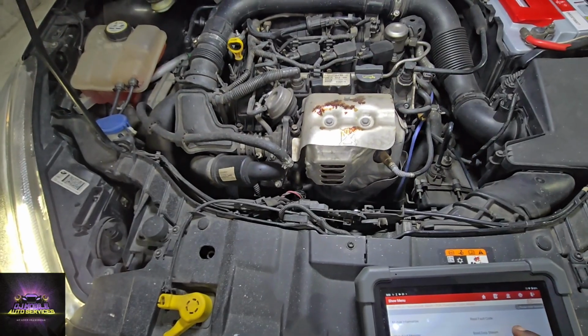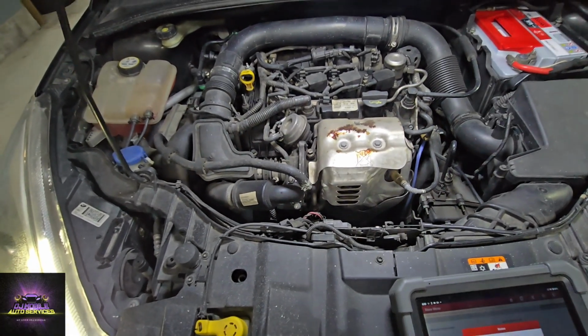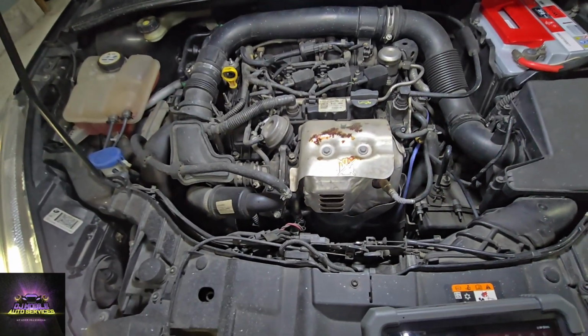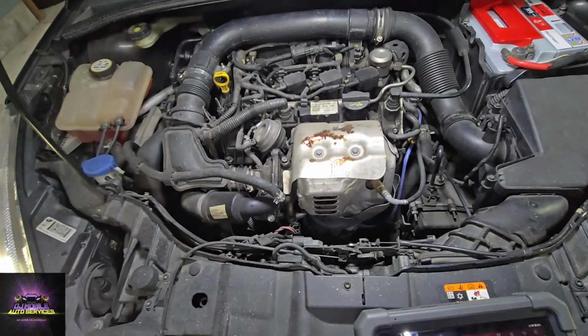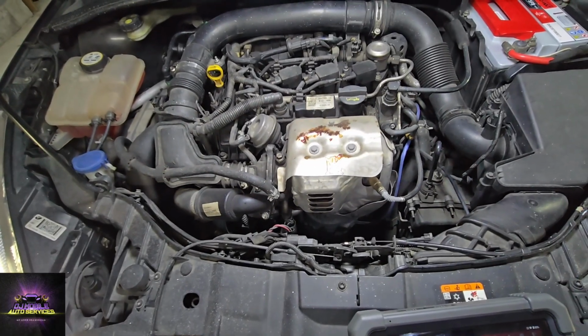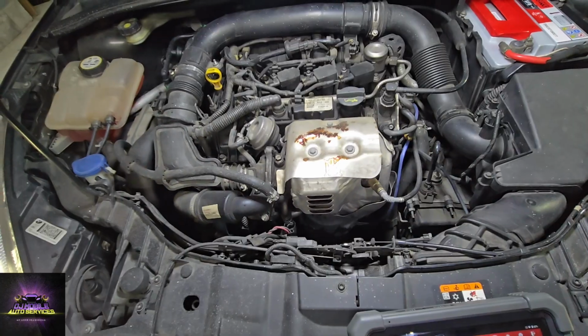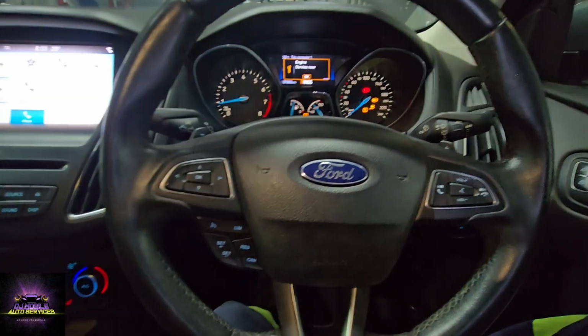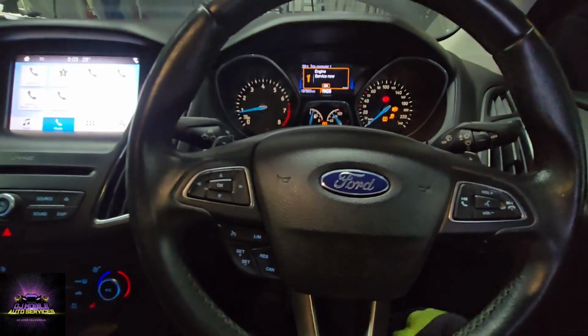Matter of fact, before I do anything, I'm gonna remove the charge pipe and let's see if the throttle plate is actually opening. That's easy to do. Just put the key on, engine off, and you look to see if the plate basically swipes back and forth. Yeah, let's do that. That's really simple before we grab any tools. Right now, this vehicle is shaking violently, and I'm not getting any throttle response at all.